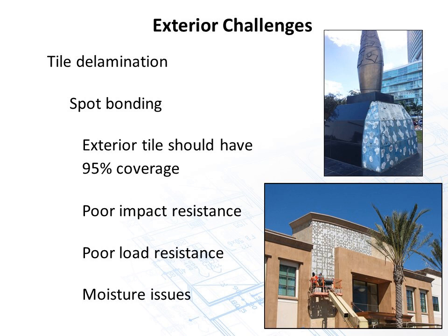Poor load resistance and moisture issues. Moisture can accumulate in all those voids and just discolor the stone or tile for that matter. This is a big, big issue. As tiles become larger, installers don't do the proper substrate preparation. They really don't know how to flatten out a wall other than put more mortar underneath the corner. This works okay for some of the masonry industry, but not for the tile industry, not to mention large format tile.